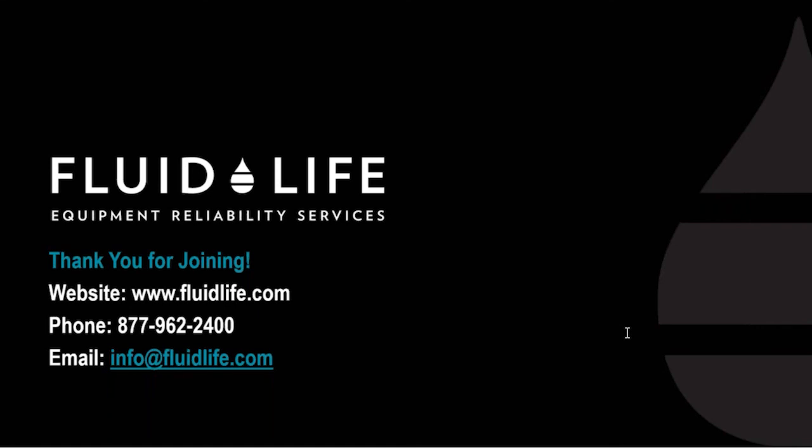So I'm fielding a question here that says, where do the contaminants come from? Sodium, potassium, silicon in the ICP test, and how do we interpret these? Well, sodium, potassium, and silicon, it really just depends. With potassium, you're not necessarily going to see a lot attributed to coolant, for example, or inhibitors to coolant, because it's not necessarily near all the cooled systems most of the time, especially in certain platforms that I'm pretty familiar with.